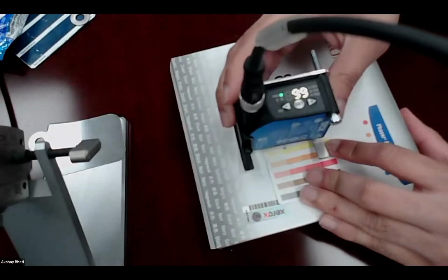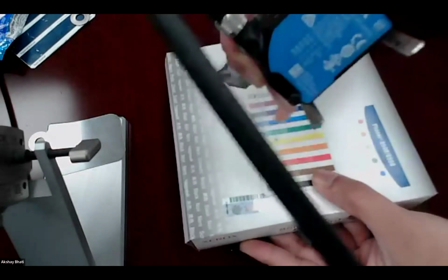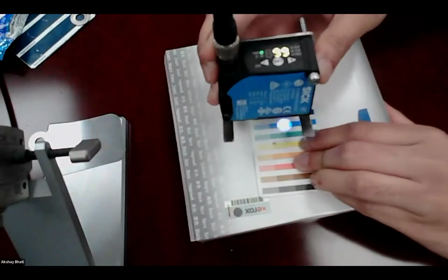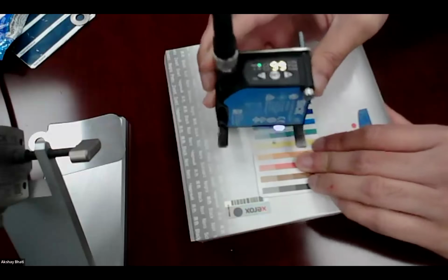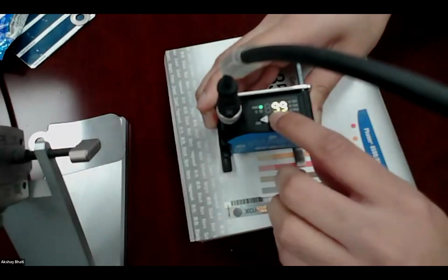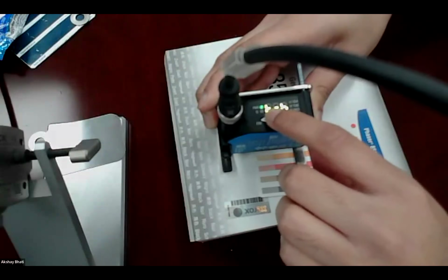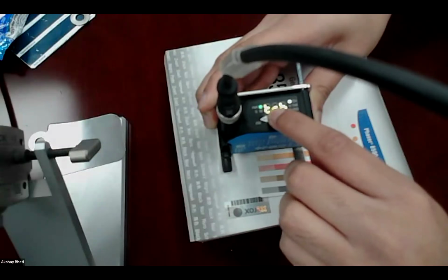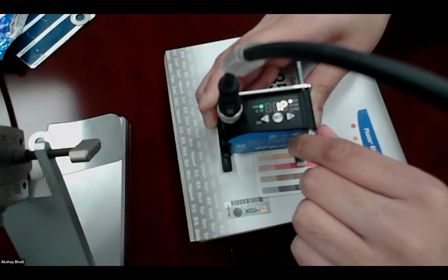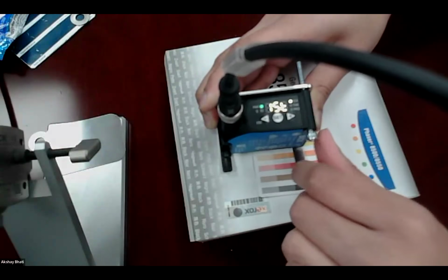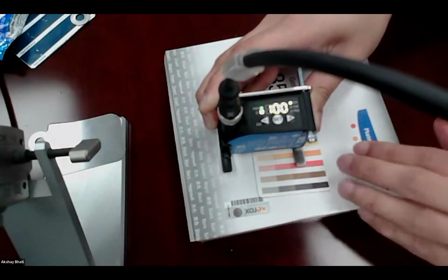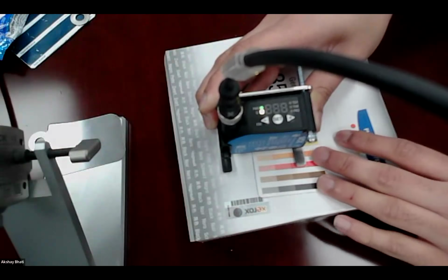And then the teaching process is really easy. As you can see, my target is this second shade of green, and this is my light spot. So if I put it here on the light spot, I'll press set. Now it says TCH, which is teach. I press set again. It says 1P, which is 1 point. So I'm in 1 point mode, which is a color mode. I press set again, and it says first point, set again. It learns the target, and 100% teach and done.